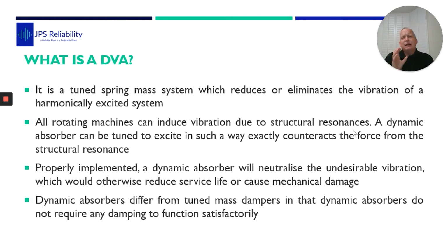They're different than tuned mass dampers. So you think of the Tokyo Tower with a huge ball when the earthquake comes, that's like a tuned mass damper. We're doing a dynamic vibration absorber. You might know these from suspension bridges. When the cables come down, they've got these little wire things. So when the wind hits a certain speed, these will vibrate. And all the power line overhead cables, they're going to be resonant at a certain frequency with wind aeolian flutter. But they will have those little dynamic absorbers. And I even think some old cars in the States, they had some exhaust problems, rattling under cars. They have a dynamic vibration absorber to solve it.